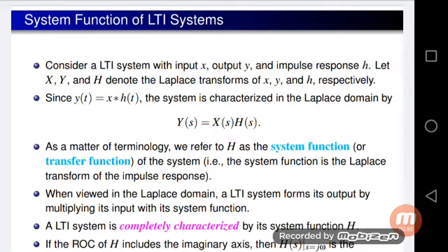Since y of t equals x convolved with h of t, the system is characterized in the Laplace domain by Y of s equals X of s times H of s, where H is the system function, X is the input and Y is the output. As a matter of terminology, we refer to H as the system function or transfer function of the system.